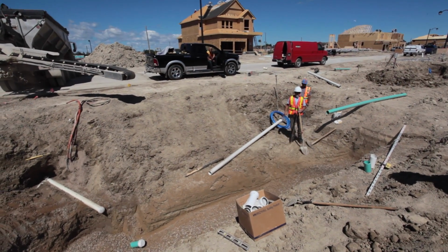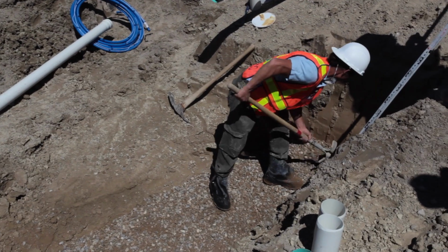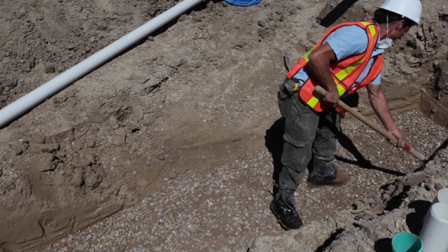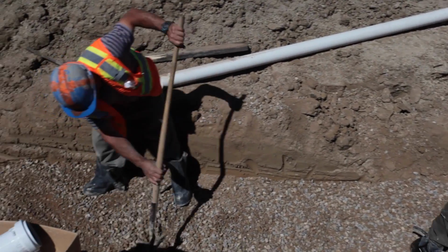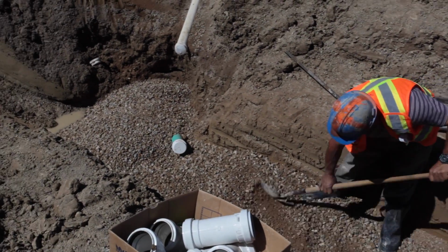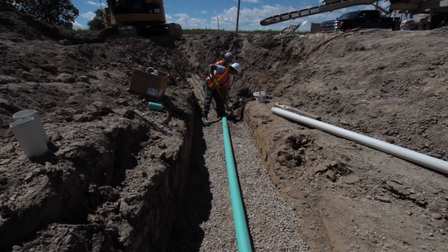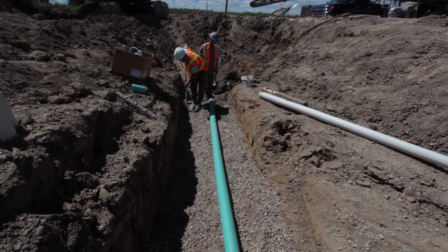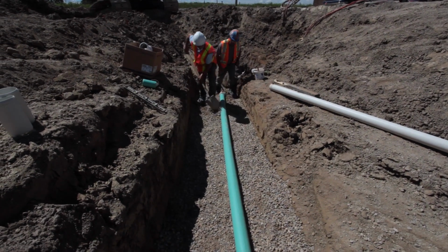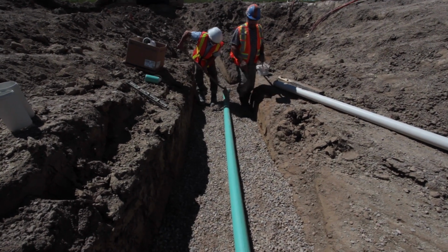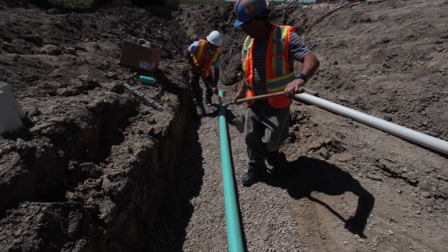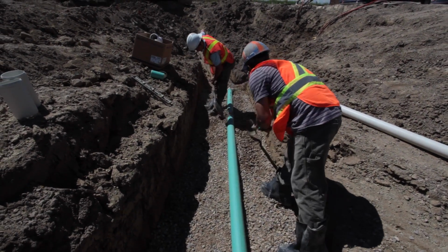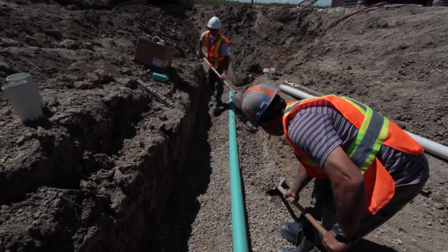Where bedding is required, a depth of 4 to 6 inches is recommended. When covering over pipe, ensure a minimum 12 inches of cover for protection. For haunching, stone should be placed on both sides of the PVC pipe. This is essential to the PVC pipe's ability to hold vertical loads. All pipe embedment and backfill should be selected and placed avoiding boulders, frozen lumps, and debris.